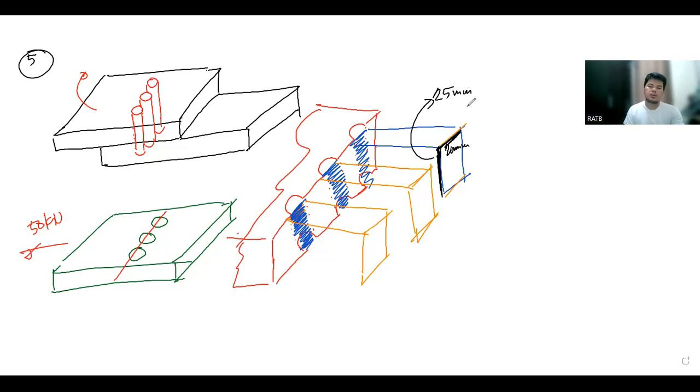Now, if we analyze again the three stresses: if the problem is asking for the normal stress, it is force over area, but the area considered is the perpendicular area, the one subjected to the force F. If asked for the shearing stress, force over area, the area to be considered is the parallel area, the cross-sectional area that holds the two plates together.